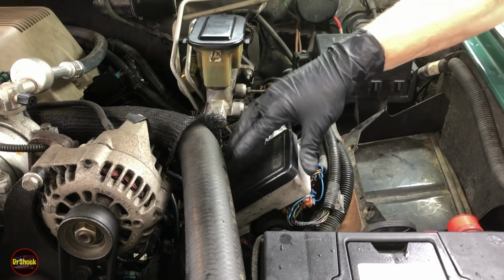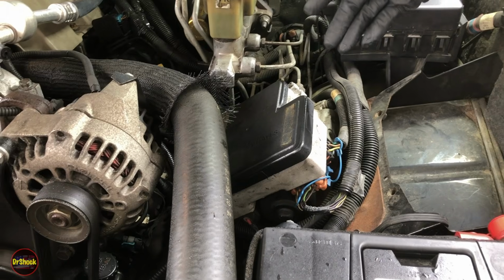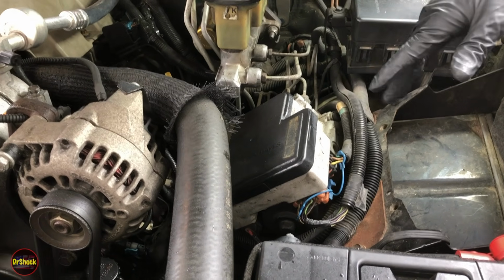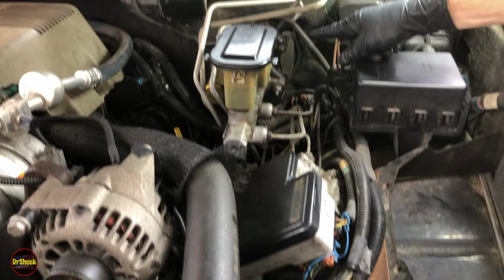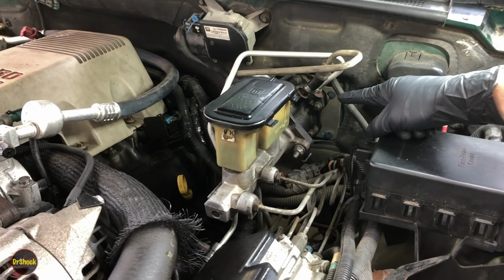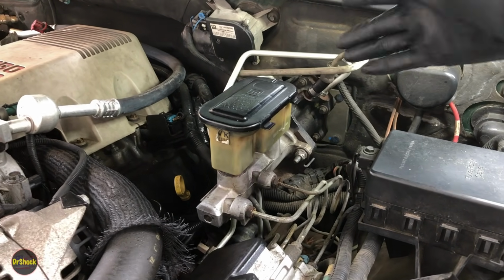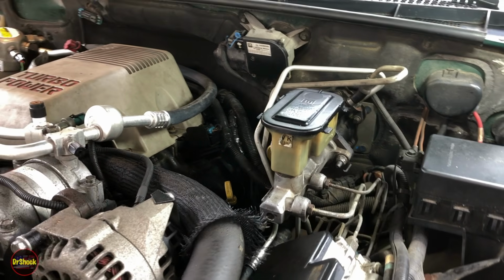But we can still see our EHBU here, and you can see it cosmetically looks just like the one on the gasoline engine, even though these, like I said, are going to vary. You can see over here that the booster is hydraulic, not vacuum. It's powered off the power steering pump instead of being powered off of the engine, because obviously there's no vacuum to supply from a diesel engine.